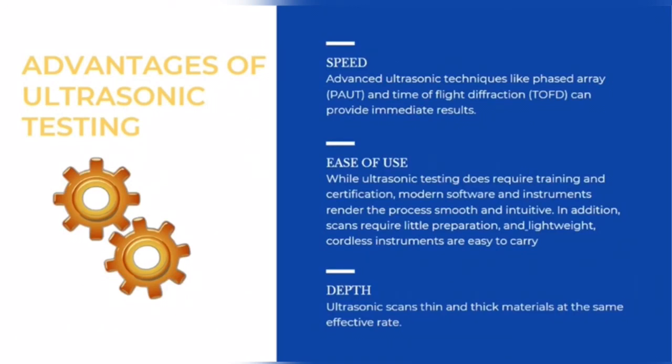Second, in terms of ease of use, while ultrasonic testing does require training and certification, modern software and instruments render the process smooth and intuitive. In addition, scans produce little vibration, and lightweight, cordless instruments are easy to carry. In terms of depth, ultrasound can scan thin and thick materials at the same effective rate. It travels more deeply through material than other analytic methods, enabling greater flaw detection.